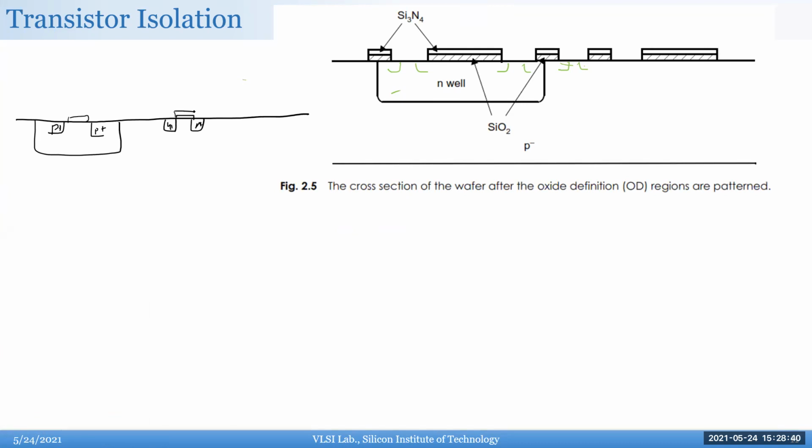Obviously a lot of you haven't done the device part yet, but essentially what you're trying to do is create a channel between these two, source and drain, using a voltage control on this gate, right? And then this whole thing is buried in silicon dioxide, and you have metal routing, right?